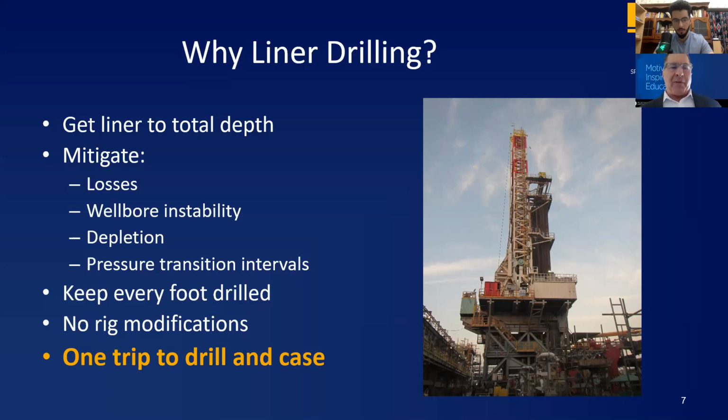Because the problem is, even though you're losing circulation through the bit, that's one thing. But when your hydrostatic or annular fluid level drops to a certain level, your formations are going to collapse on you, and that's the mechanism for stuck pipe. Through liner drilling, due to the close proximity of the pipe to the wellbore, you can mitigate this by having a slower rate of fluid drop in the annulus. And I hope you all have some questions on this because it is a real thing.